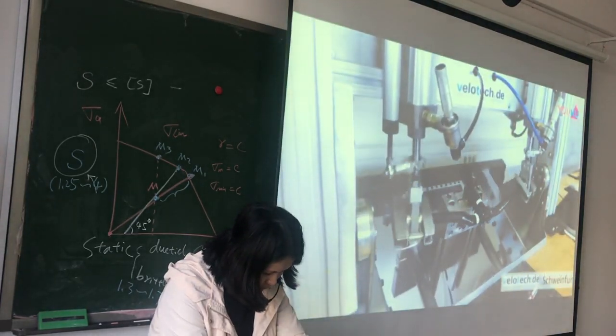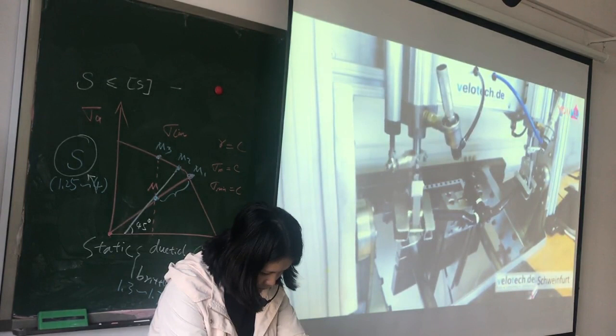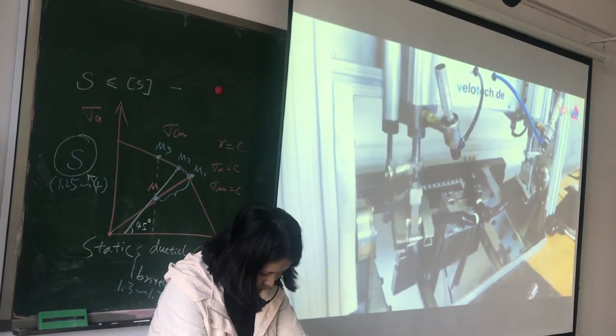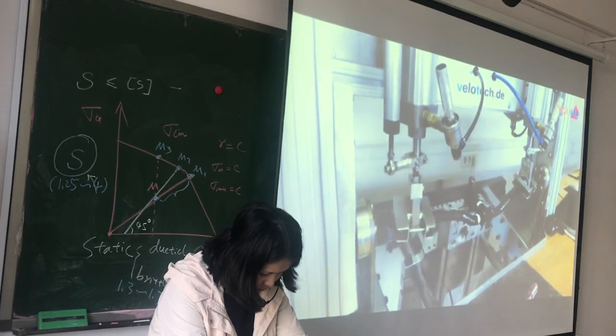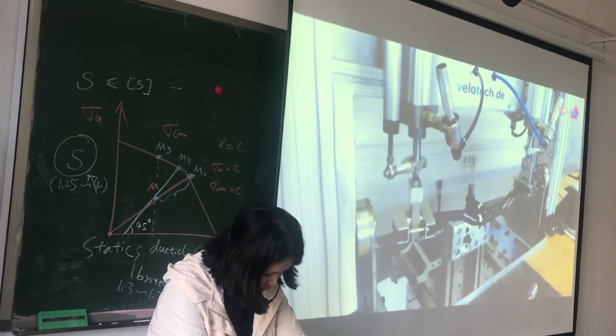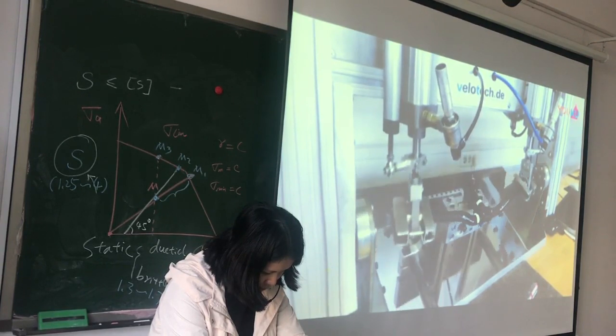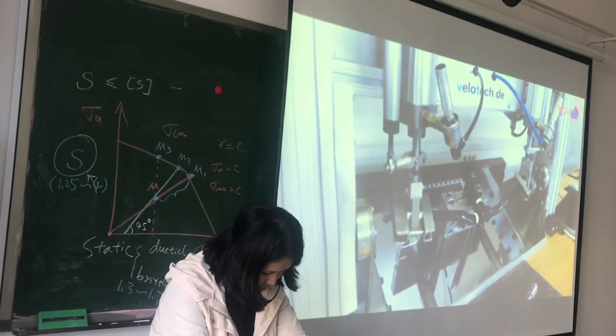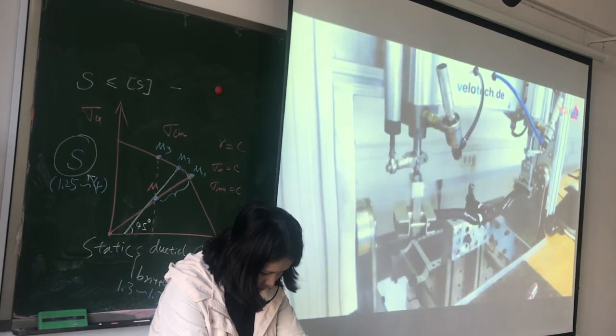In this test rig, critical bicycle components are loaded similarly to practical use. Stem and handlebar must endure the typical bending and torsional loads for a sufficient number of cycles. Only then they are approved for serial production. Moreover, the fatigue strength does not only depend on the material. The mean stress has an important influence, the shape, the surface quality, environmental conditions, and much more. Not an easy story.